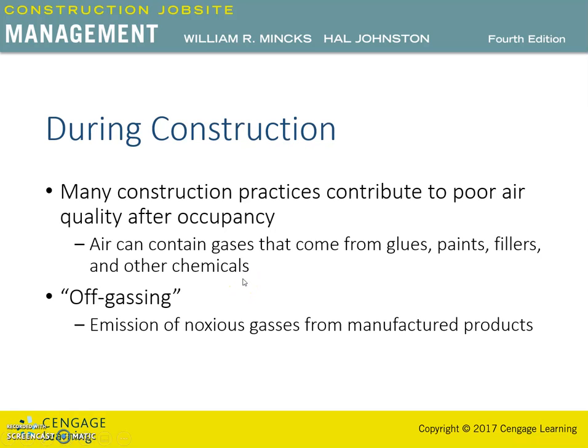The term off-gassing is often used to describe the emission of noxious gases from manufactured products. So the construction team needs to avoid such materials or have them off-gas prior to installation in the facility. This ensures that the gases will not be trapped in a new structure. The carpet layers will often expose their carpets to the outside air for a period to remove any possible problems.